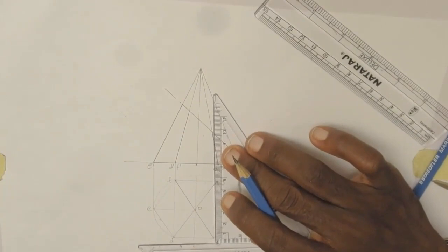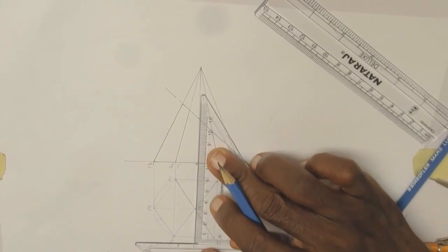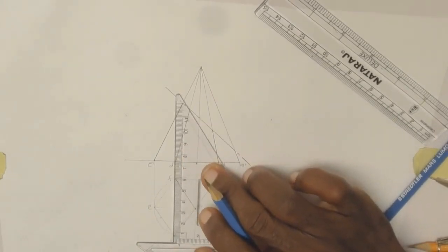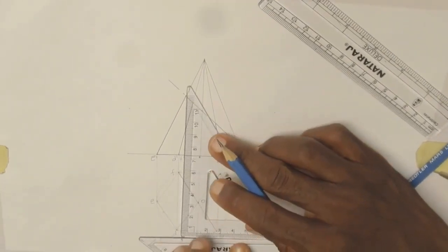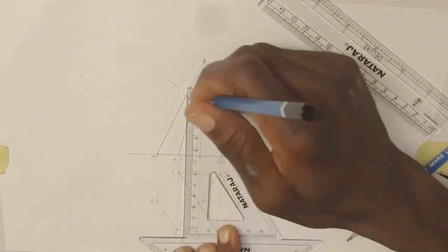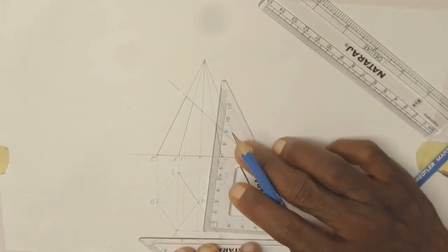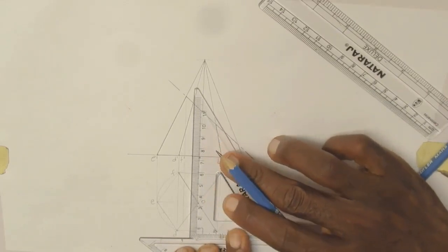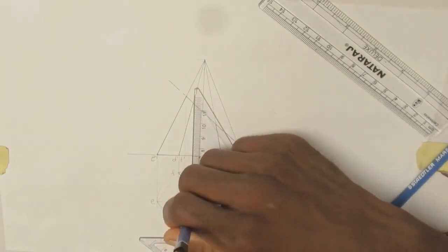All right. So after that, we need to also determine the slash surface, or the truncated surface on the plan. So we have to project from the front view to the plan to determine those points. So we project the first one, which is along the E line, vertically downwards. All right, then we go to the next one, which is along D and F. We project that one vertically downward.